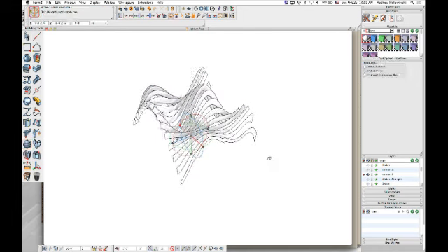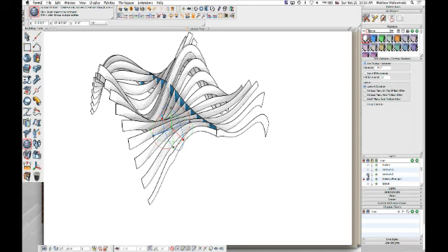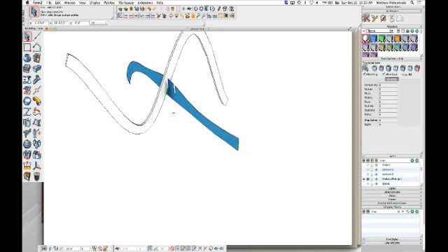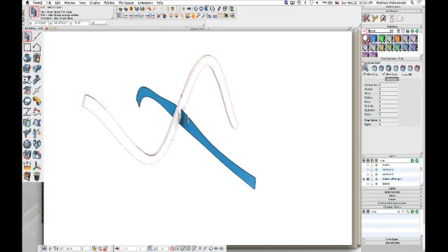Okay. So as we go through that, we can cut those contours in this direction, cut them in the other direction here. All right. And then what we need to do is cut the actual notches out of there. And so what we do is we use the thicken tool to thicken those 2D cross-section cuts, whatever the thickness of the material is that we're going to actually cut out of. And then we can actually do a surface split and cut that thickness out of each of those. And you don't do those one by one. You actually do it in one shot. You grab all of them in this direction. You grab all of them in the other direction.